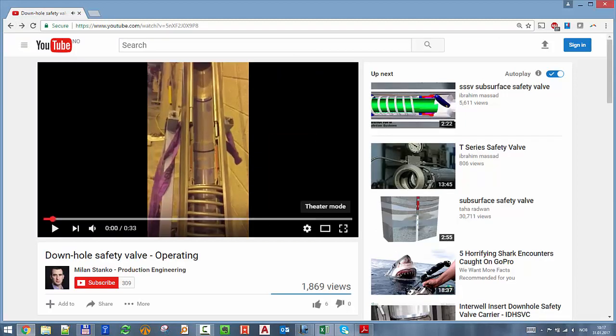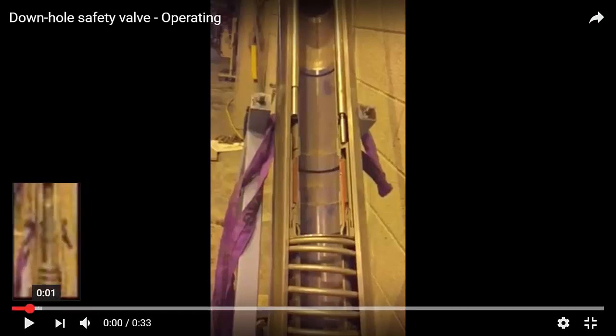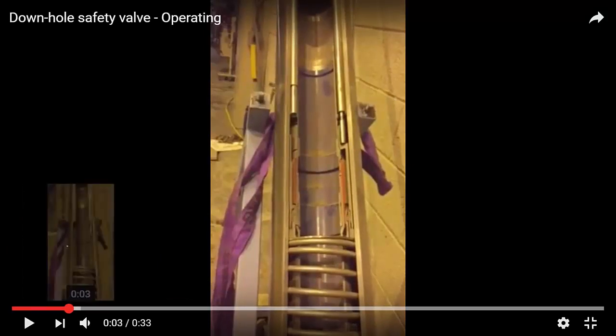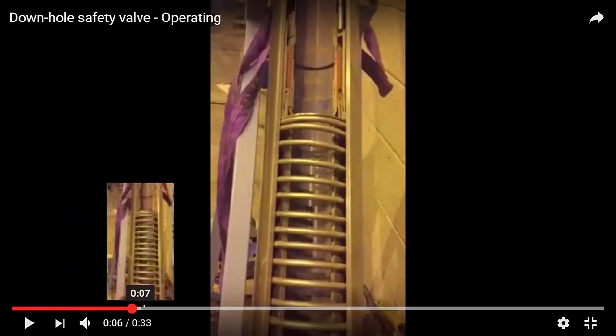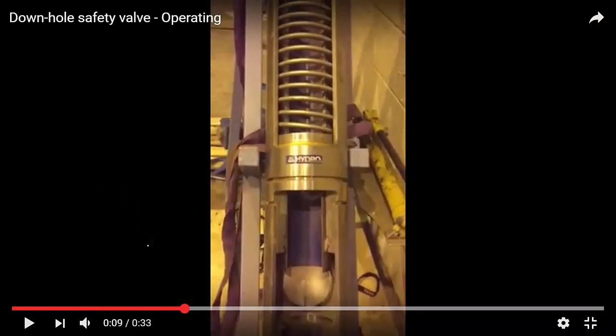That's the valve we have here, and maybe one day we will go to the lab. But you see the piston, which has hydraulic fluid from the surface inside, is pushing this shoulder that is in turn moving the sleeve, and it's also competing against that spring, and that spring is being compressed. So really it's the spring that accumulates energy, and the spring is what is going to move the sleeve and allow the flapper to close.